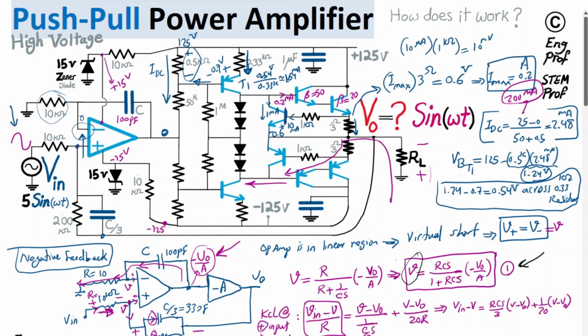So it's good enough, because we need a minimum of 1 milliamp through the diodes. We just need 0.2 milliamp to be fed to the base of the Darlington transistor to be able to support the maximum planned current, 200 milliamp at the output. That's all we need. So the fact that we have this current at the collector of T1 being equal to 1.64 milliamp is a good sign. It means we have the proper current for the circuit.